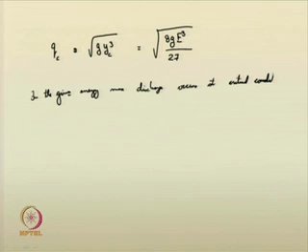Okay. If that energy is critical, then you have maximum discharge. So, you have E equal to 2.204 meter. For this specific energy to have maximum discharge, you have to see that the energy is in critical condition.